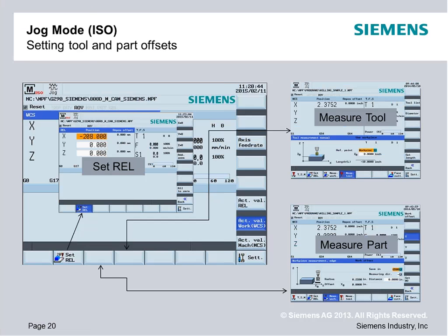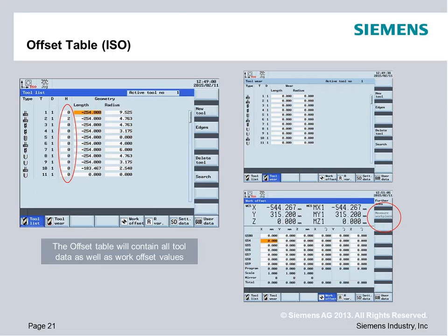As I start to crank up my feed rate, as we finish this segment of it, you're going to see it jump over to op2 semi-finishing, and then even to op3, the finishing routine. So it's always keeping track of speed and surface quality and tolerances of the part program as it's running right here.